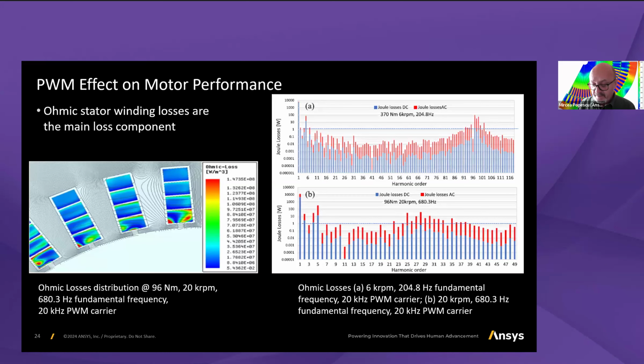With this type of waveforms, during the optimization, it's possible to calculate performance of the machine. And here we are looking to one aspect, meaning that inside the stator, I mentioned that the winding for this machine is a hairpin with 4 winding layers or 4 conductors per slot.